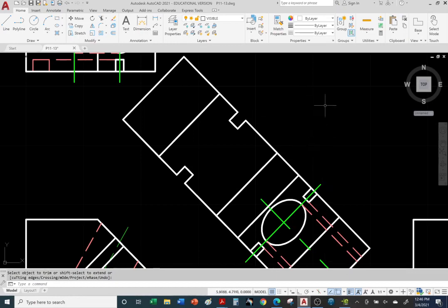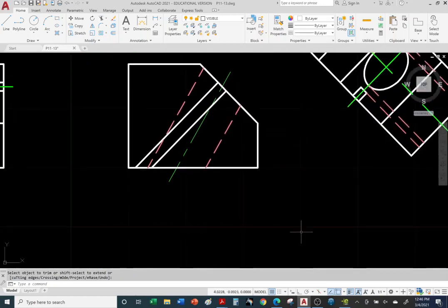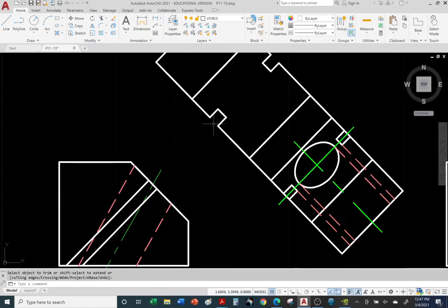All right, so you can see my cursor, right? It's vertical, horizontal. We're going to angle it. We're going to angle our cursor. And as you may already know, maybe forgot, this red line and our green line, this is our vertical axis, horizontal axis, and this is the origin, 0, 0, right? X is 0, Y is 0, there's the origin. So we're going to use our own coordinate system, and we're going to call this corner our UCS, or our axis system, and this will be our new origin. And we're going to angle it so it follows the auxiliary view. All right, so let's create our UCS.